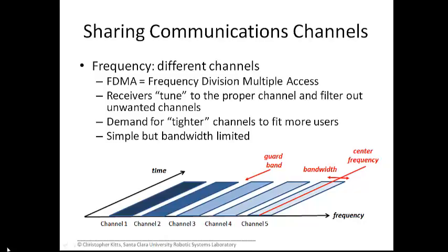And each of our channels is separated by a little bit of buffer called the guard band, and that allows each of us to simultaneously use the radio spectrum, but we're all doing it at different frequencies, and we're using equipment that when we transmit tries to limit our broadcast to that frequency, and when we receive tries to filter out anything outside of our particular channel. And that way we can all use the spectrum at the same time.